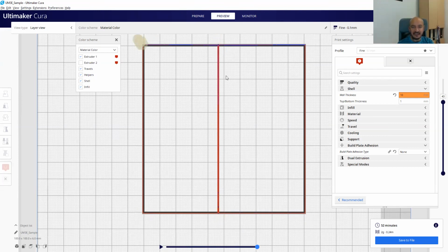The main philosophy is that it's better you don't perform any fast travels. If you avoid them, manufacturing time will be decreased and the quality of your manufacturing will be better. So if it's possible, you should always avoid using fast travels, which means using G0 commands. Without deposition, the head is moving from one point to another point. And this is how manufacturing is performed, since, as I said, a 2.5D shape is performing the same operations on top of each other.